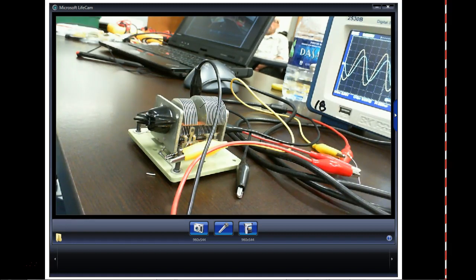So we end up with two types of power in the circuit. We end up with what we call true power and apparent power. And this is what you pay for. You pay for apparent power unless we do something. So anytime we get capacitors, and if I was to put DC on this, I'd have no voltage drop across the resistor because DC sees it as an open circuit. We have to have AC to get what we call capacitive coupling between the two plates.